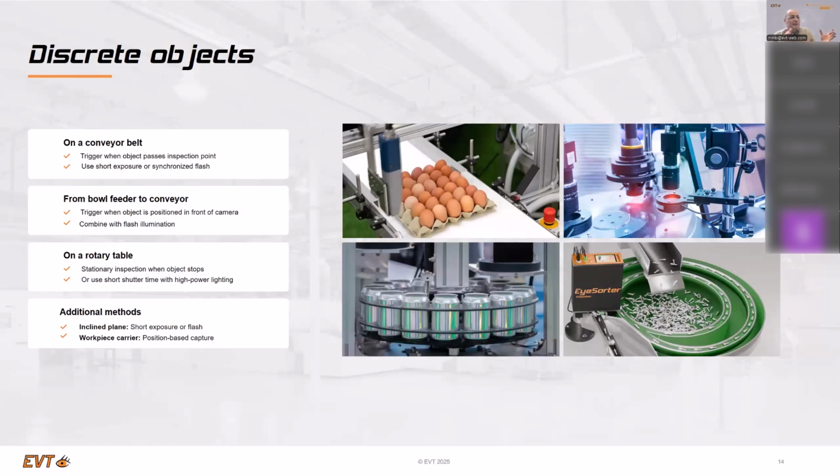And today, you simply attach a color camera on top of the belt. You get a trigger when the tray arrives, and you capture one image and you count it, and that's it. No problem. So the choice of the right sensor, light, and lens, or the right combination to make the solution between, let's say, 5 years ago and today changed totally.